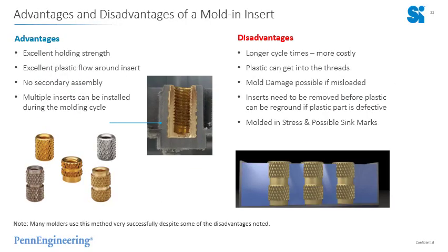Advantages and disadvantages of a molded in insert. Let's go over the advantages first, and if there's one thing you take from this slide, please realize that the performance of a molded in insert, how it performs with pull out and torque out, this is the best method. This will have the best values of all the other installation methods.